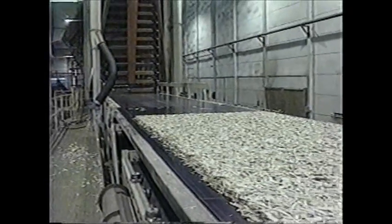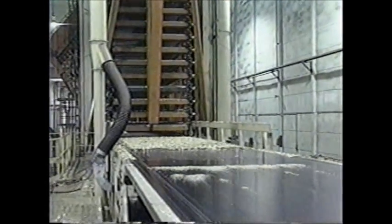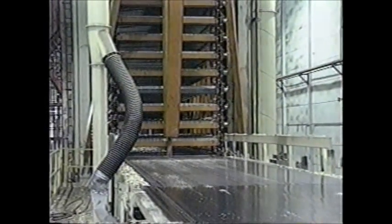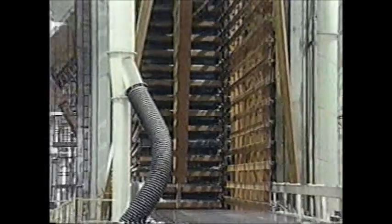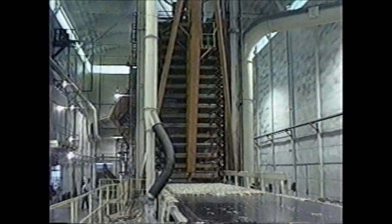The OSB mats are placed in the press charger one at a time while the press is closed. The loaded charger discharges an entire charge into the press, pushing the last charge out into a waiting set of trays. After loading, the press closes and the curing cycle begins. Meanwhile, the press charger is reloaded.